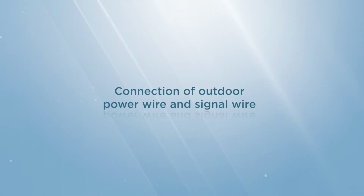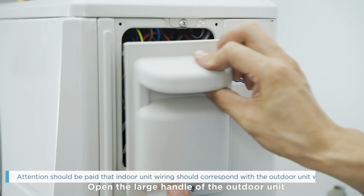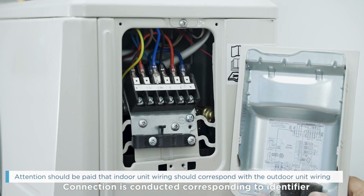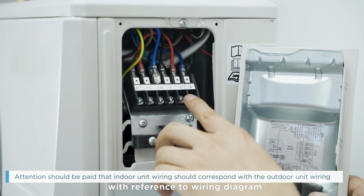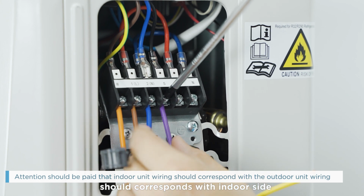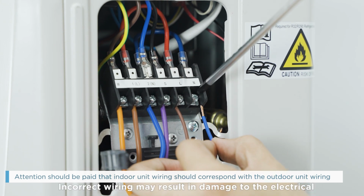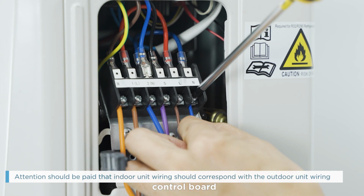Connection of outdoor power wire and signal wire. Open the large handle of the outdoor unit. The connection is conducted corresponding to the identifiers, with reference to the wiring diagram. Attention should be paid that the mode of connection should correspond with the indoor side. Incorrect wiring may result in damage to the electrical control board.